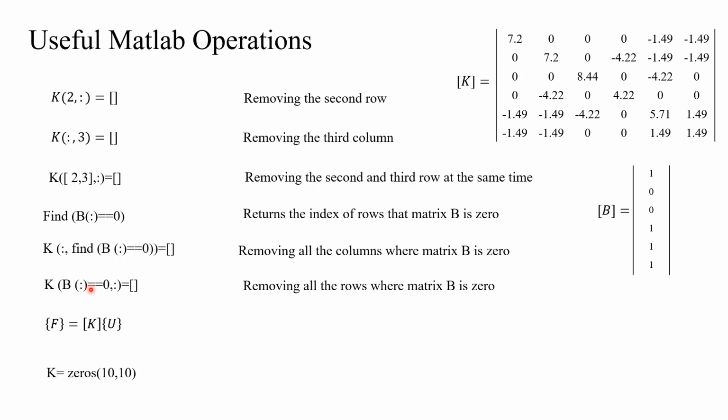returns the indices here. And for solving the FEA equation, in FEA we use this all the time, KU equals F. I rearrange it to find nodal displacement. That's the first variable that we are going to find. So we can use inverse of K times F or K backslash F, but the two are different. I recommend using this because that uses a Gaussian approach and you will get an answer.